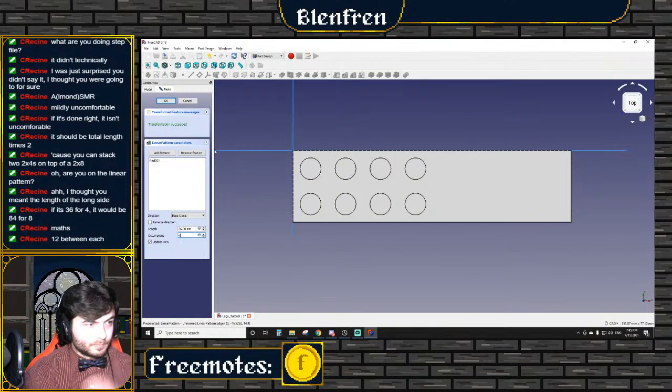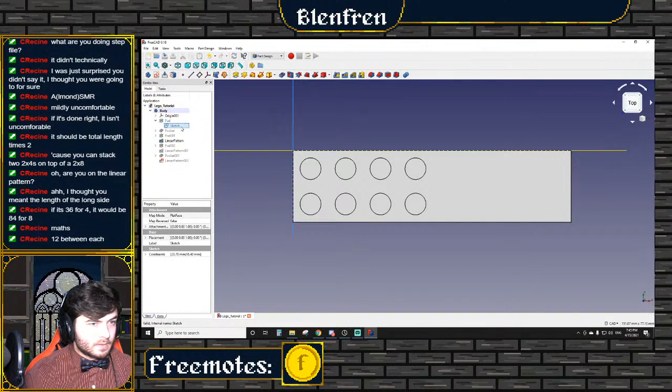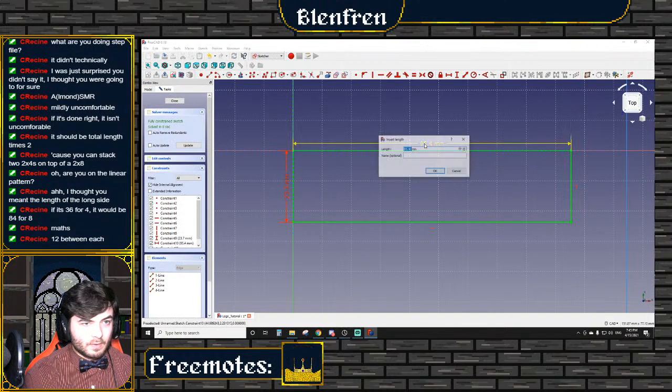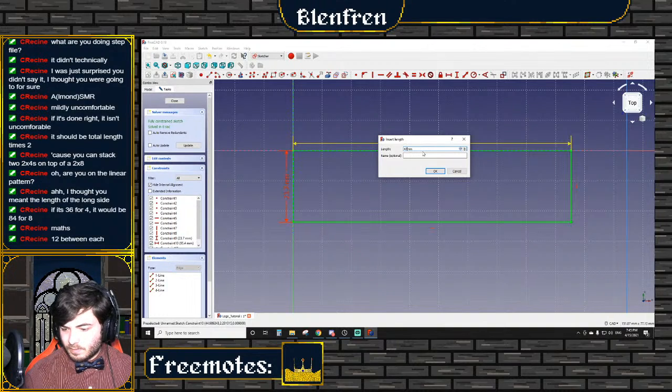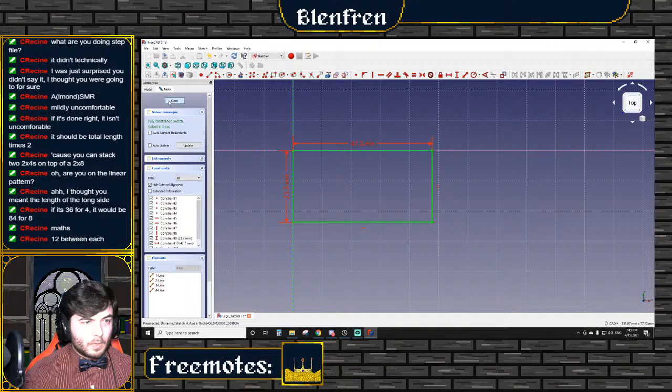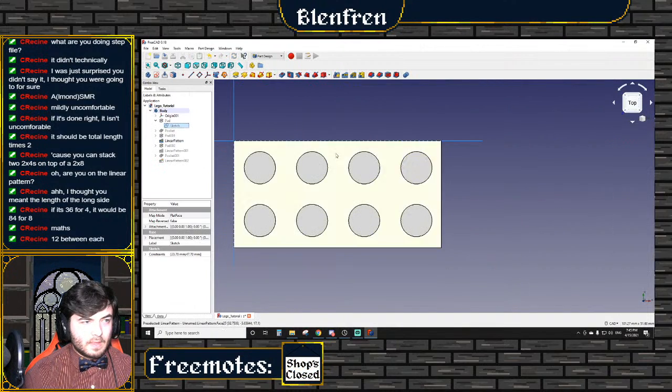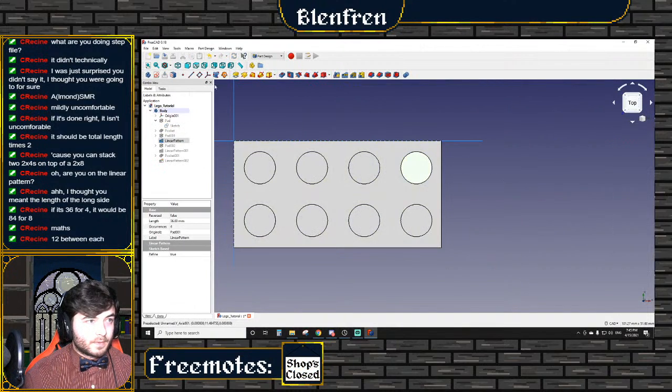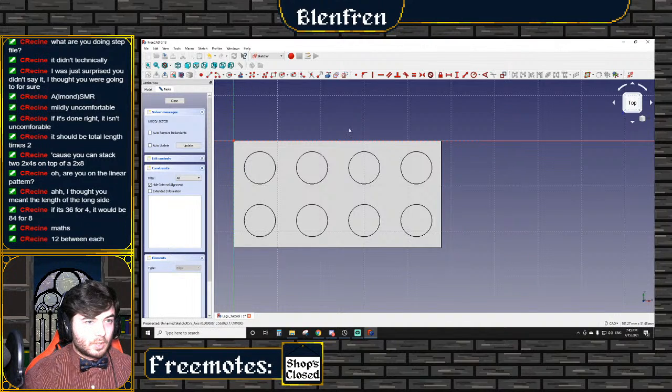There we go. Then I go back into the sketch and just cut this in half, 47.7. Then I close that, click on this surface, create a new sketch, and import new geometry. There's probably a much easier way to do this.